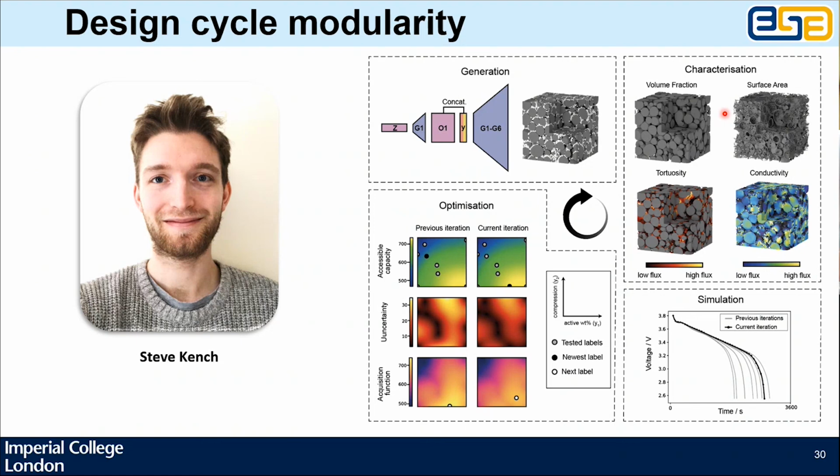So we might be interested in an energy cell where we want to store lots of energy, but we don't mind about doing it at low power, or a power cell, or we've got a particular drive cycle in mind that we'd like it to perform well on. We can ask it any question we want in the load cycle space. We then pass the results of that. So, how long did it last, or how much energy did it store at this particular rate?